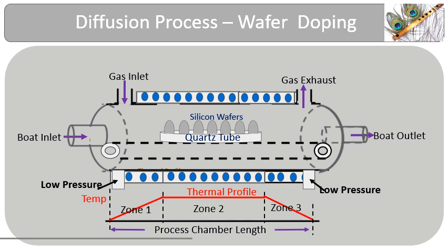Figure shows a typical diffusion furnace structure. We will briefly discuss the operation principle of a diffusion furnace. The diffusion furnace consists of a high-purity quartz tube that houses the quartz wafer boat, which carries the wafers to be diffused. The dopant pre-deposition stage is a high-temperature process where a concentrated layer of dopant is introduced to the wafer's surface. The wafers are then subjected to the drive-in step.